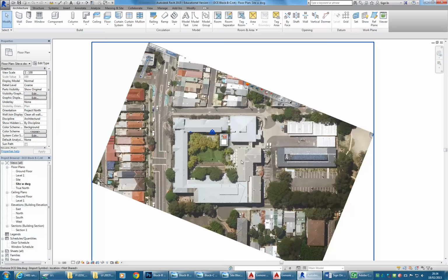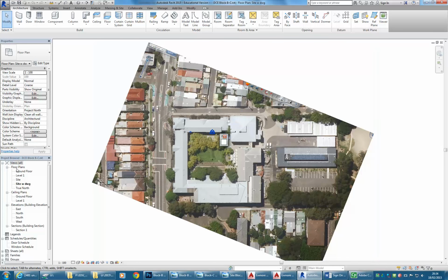And then in Revit, the main thing I want to show you is the view that you want to bring it into and how that needs to be set up. So we've got the file that I inserted the satellite image into last week from AutoCAD, remember? So I want to do the same thing basically now in a different view, or in this case a different floor plan.